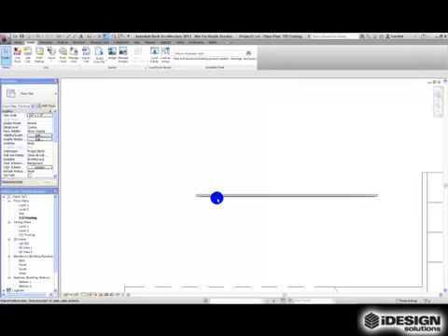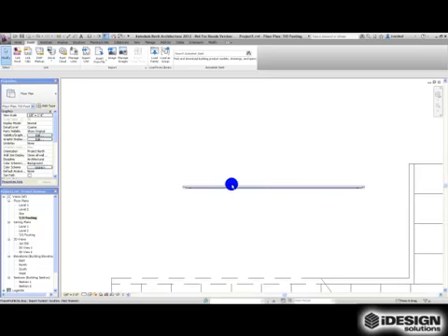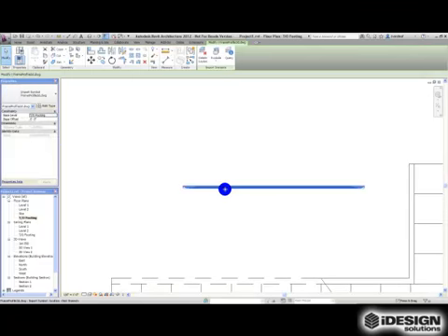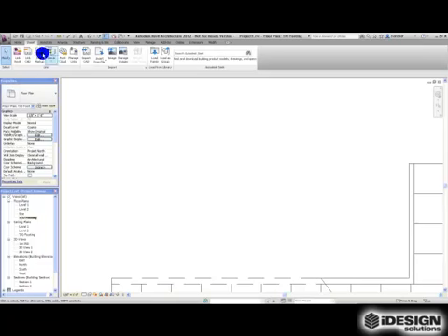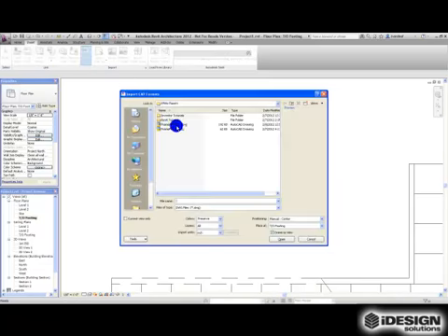Now if I come over into Revit, you see I've got one that's already prepared, but I want to show you the process. So I come up into the Insert tab, and I go to Import CAD, and it gives you a dialog box. So you choose your 3D file, and in colors you want to choose preserve colors because you want that material to stay on there, and leave layers as all because we did everything in one layer.